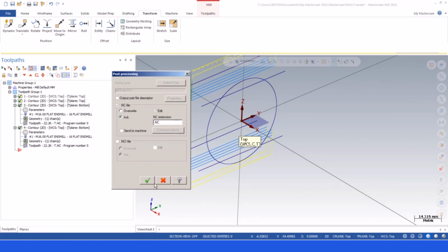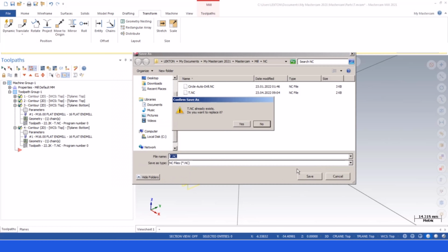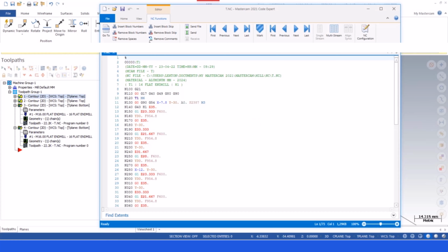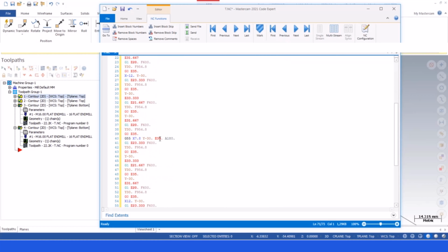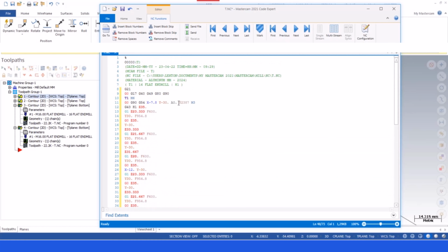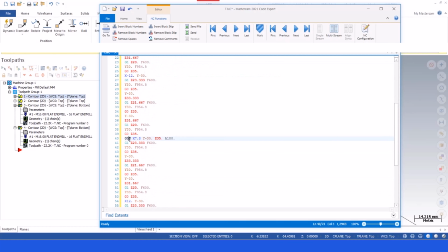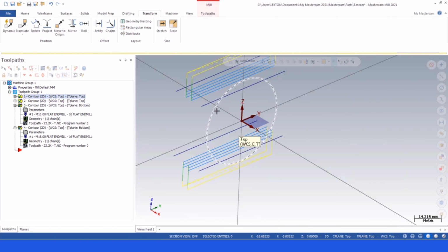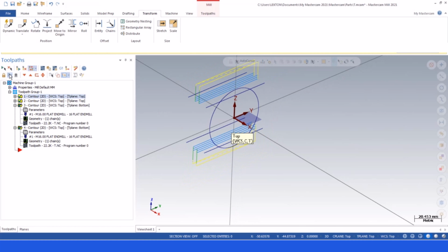So let's see our G code here. We already have that, so I can click here, remove block numbers, and let me check that this is A 180 position and A0 position. But we can also see the different working coordinate system here. We can change that. That must be the same as this. We can save that file. Okay, this is actually top to bottom.